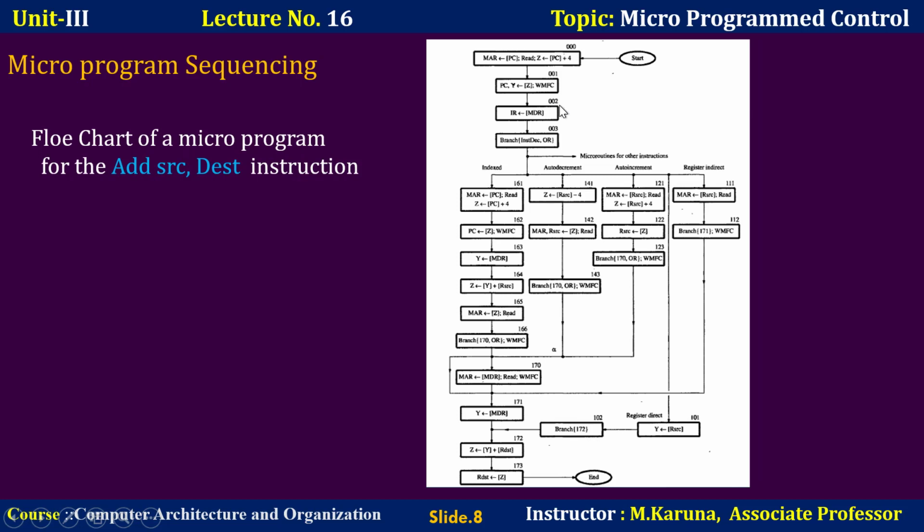So we have seen the complete instruction execution topic, where first the processor needs to fetch the instruction code, then fetch the first operand, then perform the operation on that data, and then the output will be transferred to the destination register. Here the source may be specified in register direct mode, register indirect mode, auto increment mode, auto decrement mode. For the direct mode, the address 101 is assigned to the register direct mode.